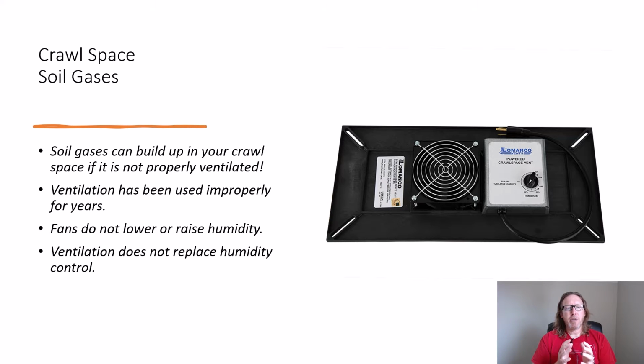Ventilation has been used improperly for years. Fans have been used to control humidity. Fans do not control humidity. They can lower humidity. They can raise humidity depending on the source of the air that you're pulling from or pushing to. So keep that in mind. It's all about the makeup air, okay?